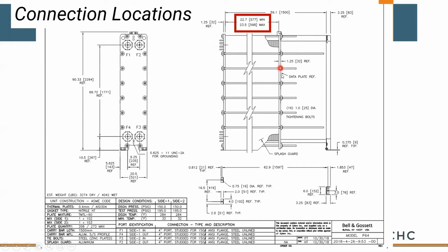If you start torquing down on this all thread and sandwich your plate super tight, what you're doing is flattening all your gaskets, and now they have no elasticity, and ultimately you're going to have to replace them. So just make sure that you're tightening to the factory dimension or recommended dimension, not to a torque.